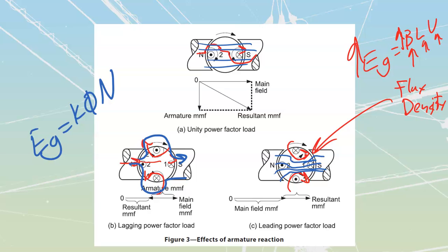Automatic voltage control is just going to have a combination ammeter that is connected with something able to change the amount of current I send through my alternator field. If you think about it, you can even design these conceptually quite easily just with your knowledge of electronics, right? The greater the amount of current going through, I can just use a transistor to amplify the amount of field current I send through, or something like that.